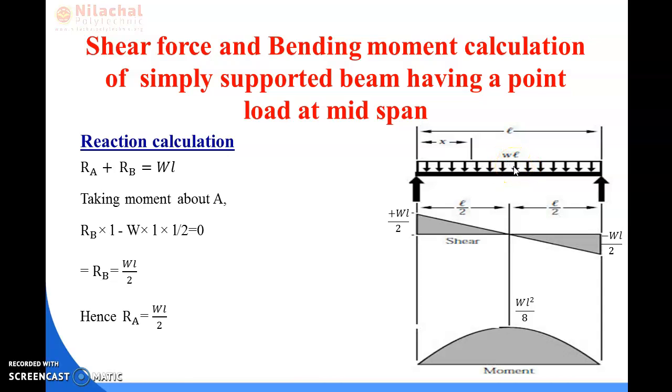So to calculate the moment for the UDL, I told you in case of cantilever, in case of UDL, the moment calculation will be load into distance by 2. So that here your load is W and distance up to this point will be L because the UDL is acting all over the span. So the total distance is L and distance by 2, that is L by 2.